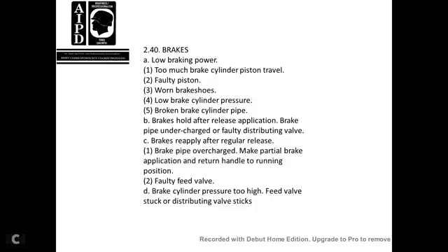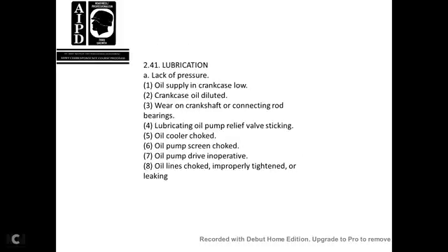240, low braking power: too much brake cylinder piston travel, faulty piston, worn brake shoes, low brake cylinder pressure, broken pipe. Brakes hold after a release application: brake pipe undercharged, faulty distribution valve. Brakes reapply after regular release: brake pipe overcharged, or partial brake application; return handle to running position. 2, faulty feed valve, brake cylinder pressure too high, feed valve stuck, and distributing valve sticks.